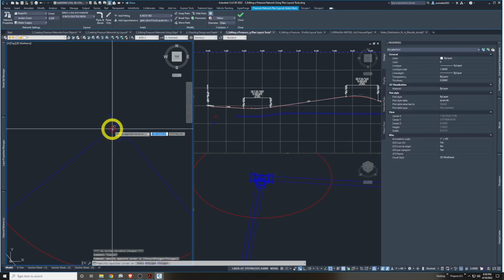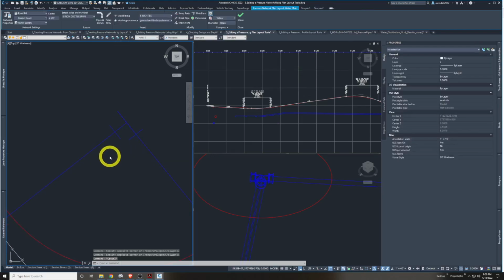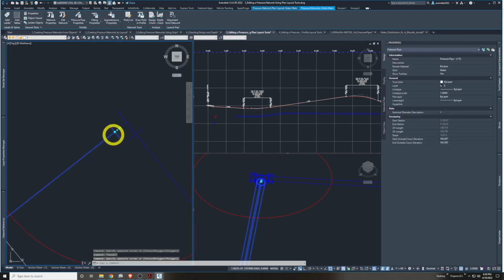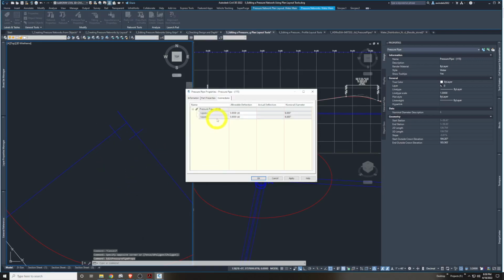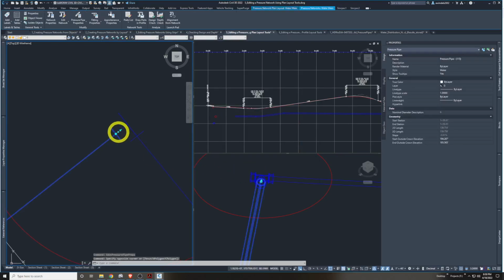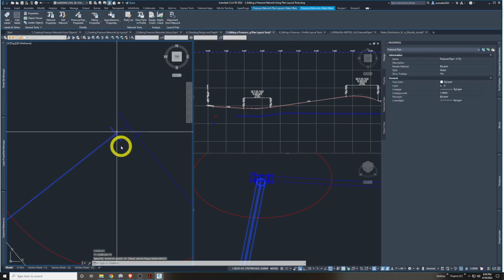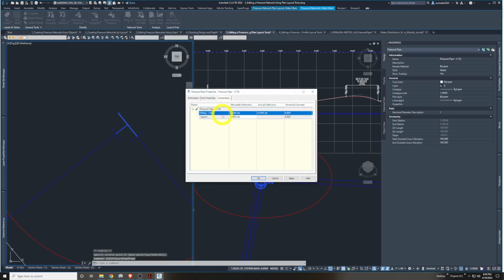And we go in here and we pick on this fitting. It's not named anything special. It's just fitting 104 for now. That's easy to rename later, but let me go back to right click pressure pipe properties. So I have it open on both ends. So this tells me that I do not have that connection. Let's hit OK. Let me go here. That should have done it. Yes, connected it now. Okay.